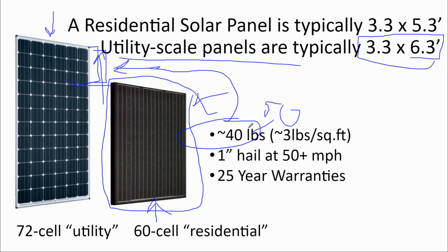Manufacturers know that solar goes outside. So the panels are designed to go outside. The manufacturers have hail test ratings. About 1-inch hail at 50 miles an hour will bounce right off a solar panel. That doesn't mean the solar panels are bulletproof, but in my experience, the solar panel is so durable and strong that it actually gives a false sense of security and durability.